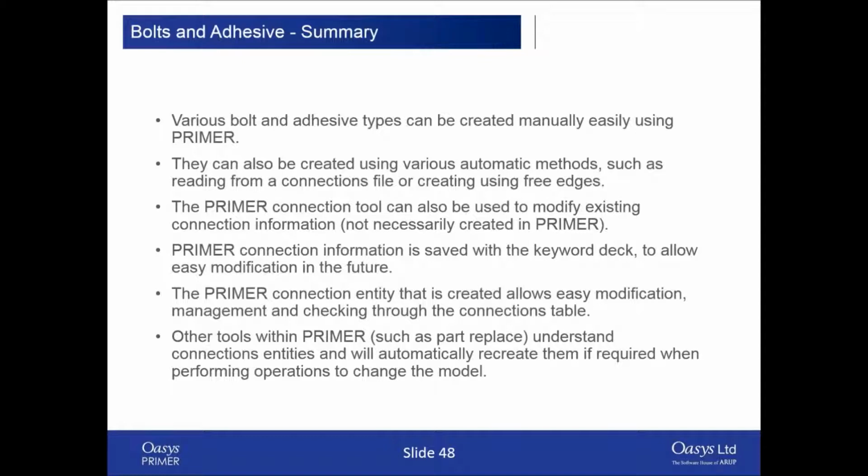So the Primer connection entity that is created, I talked about creating this connection entity on top of the FE that's actually created. That can allow you to easily modify, manage, and check the connection information through the connections table.